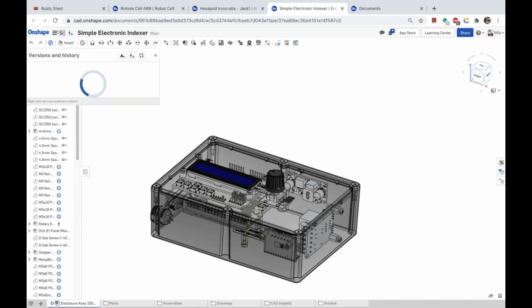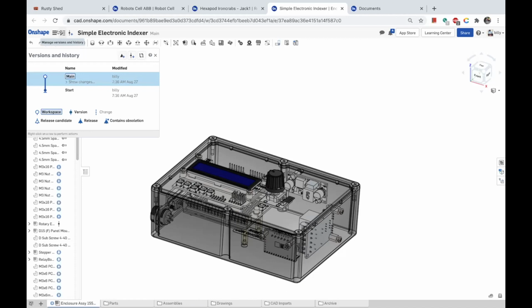Okay, so basically you want to version it. So if you're going to have a design evolve, don't put it inside of an archive folder. What you should do instead is to go ahead, version it, and then if you don't want to use any of the stuff in the past, just delete it. It doesn't go away, it comes back. So instead of archive right here, this should have just been version 1. This looks pretty good. And move on from there, okay?